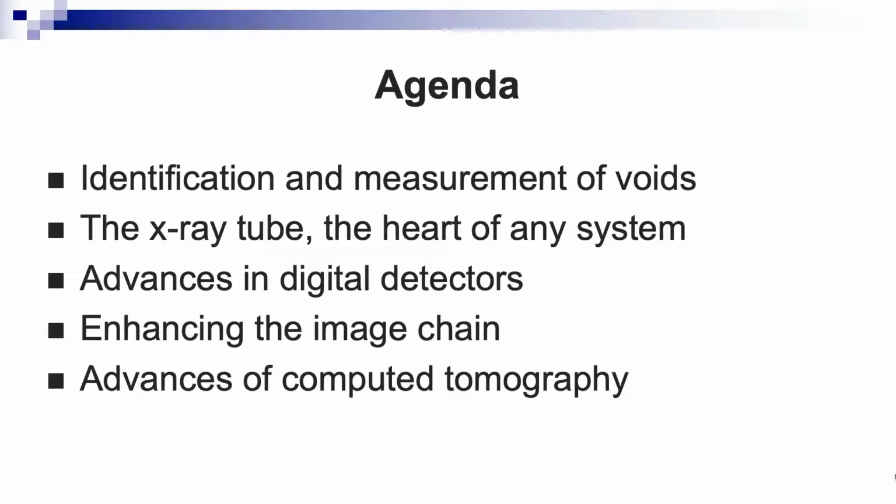Then, of course, we got bottom terminated components like QFNs, which have a central pad area, and that pad area is used to move temperature. And of course, if there's a void, you have air. Air is a very bad conductor of heat, whereas solder is a very good conductor. So to put it simplistically, if you have 40% voiding on that center pad, you reduce the amount of heat that you transfer by 40%.